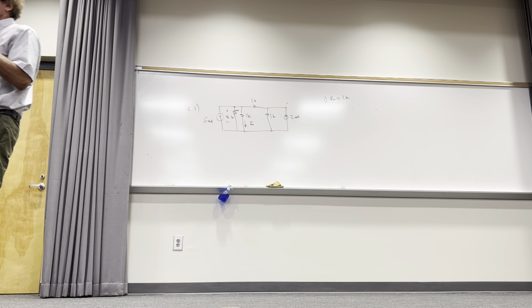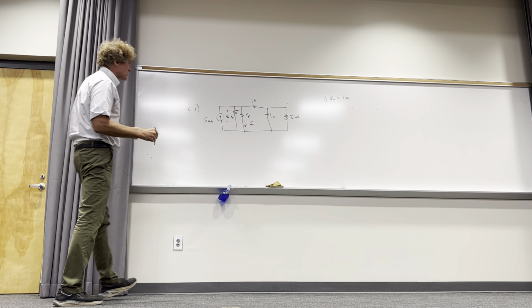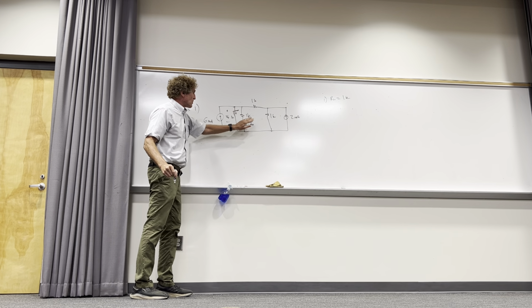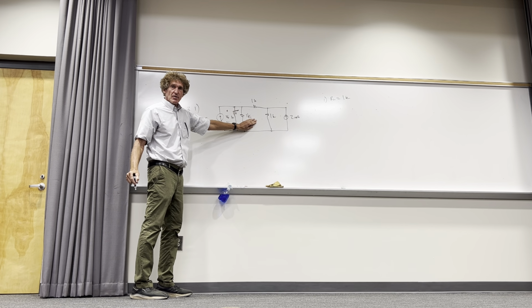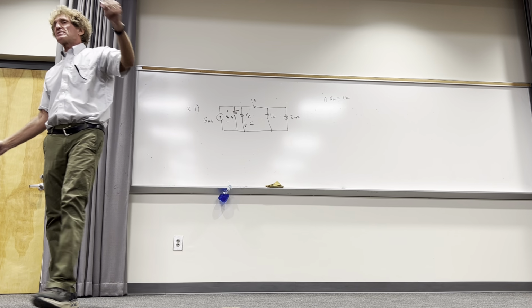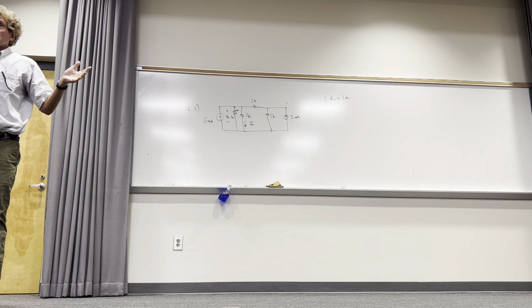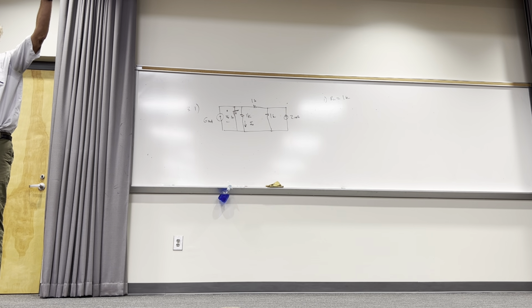Now, if you just do this blindly, they say remove the load resistor. Well, which one to remove? They're both identical, correct? How would you approach that using Thevenin? I'm asking for a reasonable answer. Just think about it. Anyone? What might you do if we're after voltage? Yes, sir. Maybe combine the two resistors and make it 1/2 K, right? You all see that?